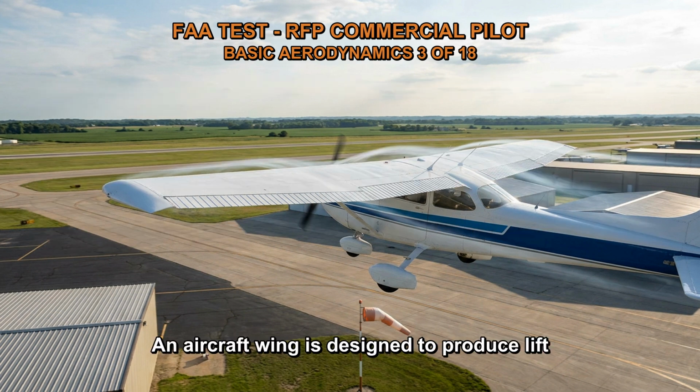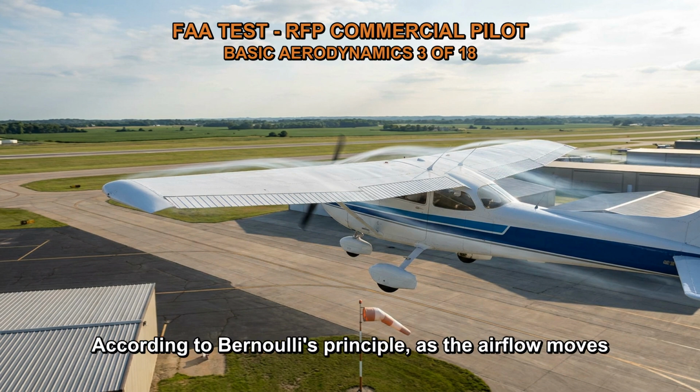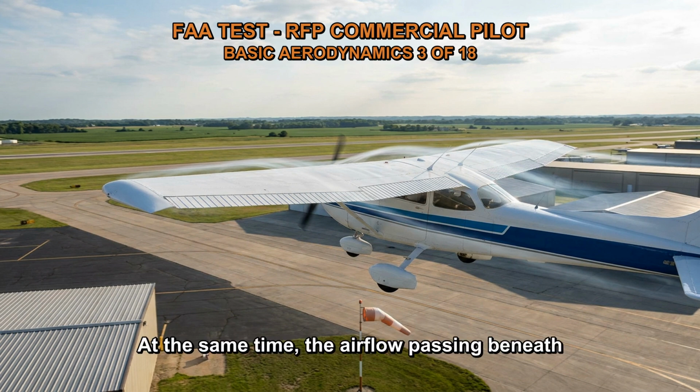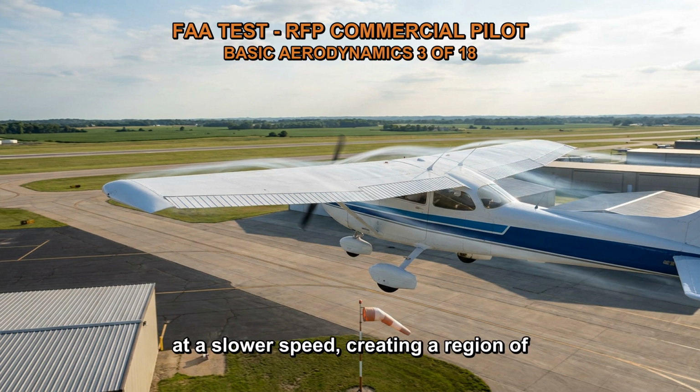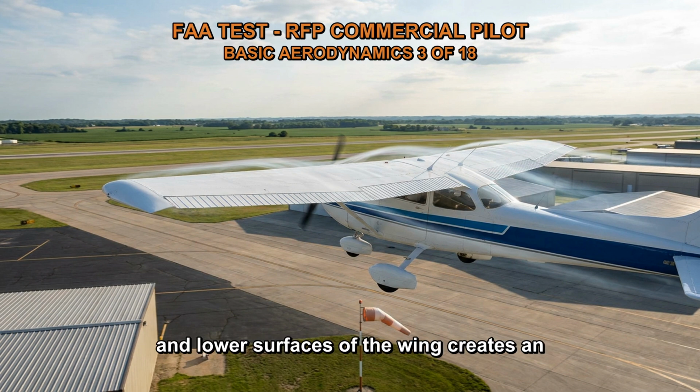An aircraft wing is designed to produce lift resulting from a difference in air pressure between the upper and lower surfaces of the wing. According to Bernoulli's principle, as the airflow moves over the curved upper surface of the wing, it accelerates and creates a region of lower pressure. At the same time, the airflow passing beneath the flatter lower surface of the wing moves at a slower speed, creating a region of higher pressure. This difference in air pressure between the upper and lower surfaces of the wing creates an upward force known as